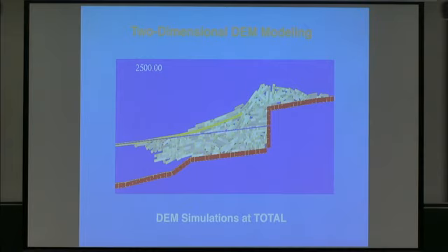So here's our intact ice sheet in yellow. And that's pushed into the structure; first initially it hits the structure. And we don't have any crushing in this model, so what happens initially is bogus. You're going to see a little chaotic breakage and so forth, but once you've accumulated a few blocks there, the sheet is able to ride up on the block accumulation, and then it begins to fail in flexure, which is what the model is designed to do.